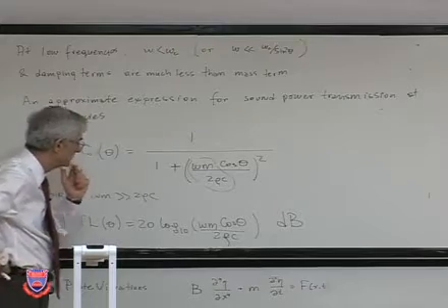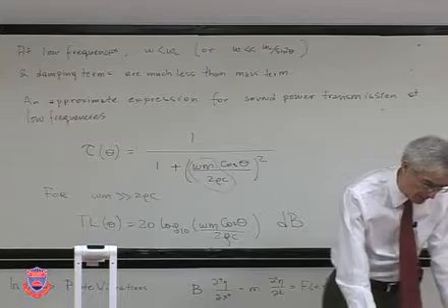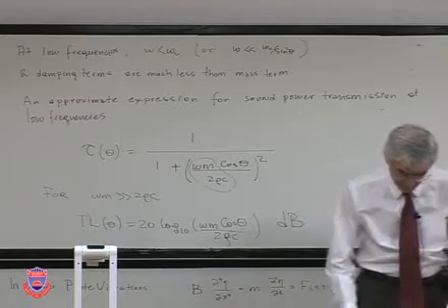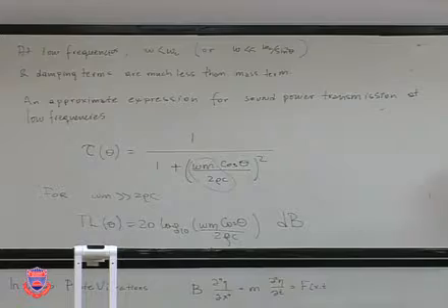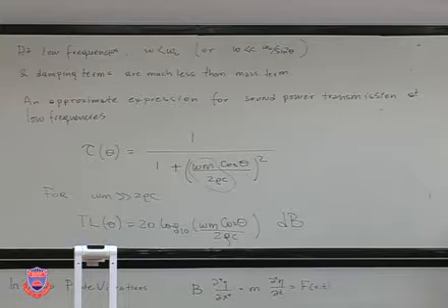So this is also referred to as the mass law in some cases. Now, this is forming the basis for noise control studies. And when you look at noise control studies, usually they will give you these equations. This is the transmission loss expression, etc. But where it comes from is what we have just derived.